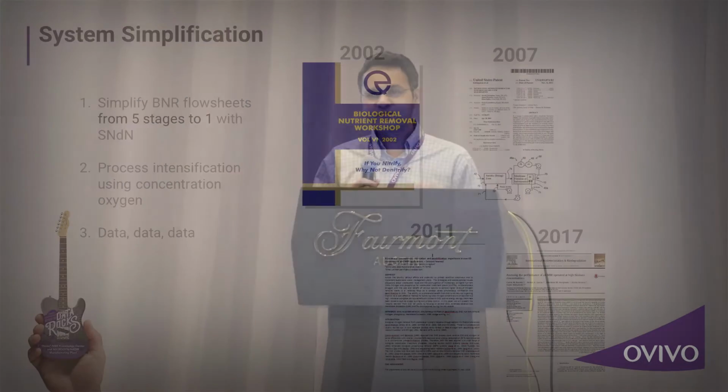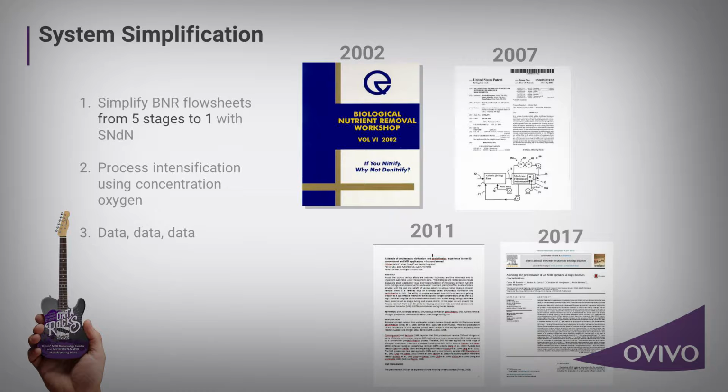2007, we took the next step and, as I mentioned earlier, the whole focus is always process plus membranes. They're together. So in 2007, we took the next step, innovated, and said, okay, how can we make the process even simpler? So we applied for a patent, which is for high solids application, which is instead of running an MBR at 10,000 milligrams per liter, you would run at 20,000 milligrams per liter. Now, when you do that, you can't really use fine bubble aeration because you're limited by the uptake rate. So we had a high rate with concentrated oxygen as well as single stage SNDN. So that was kind of the next level of innovation.